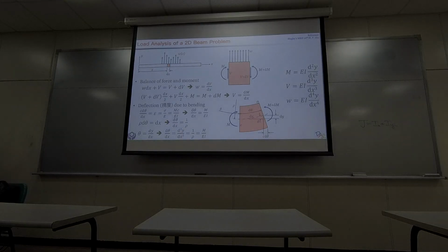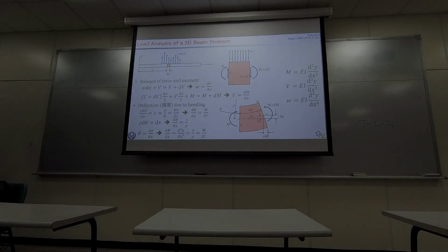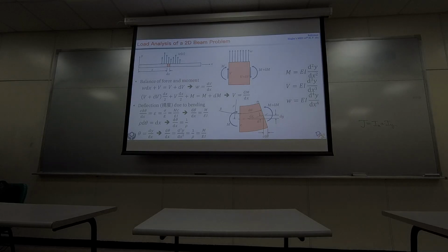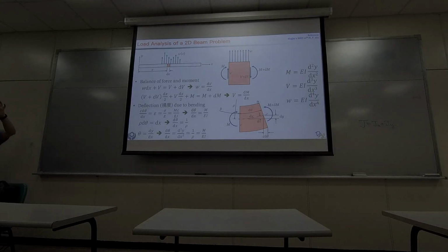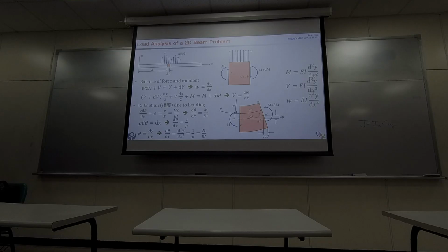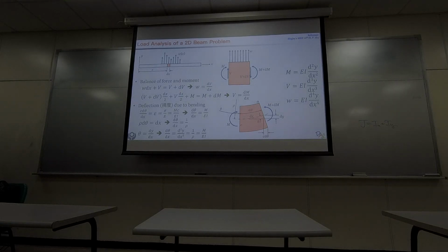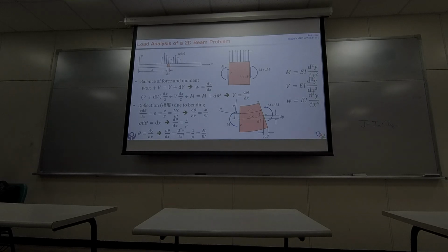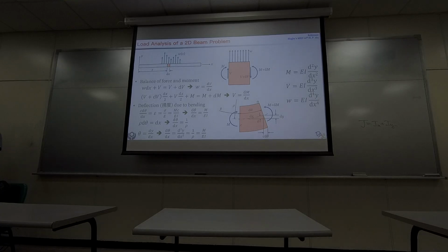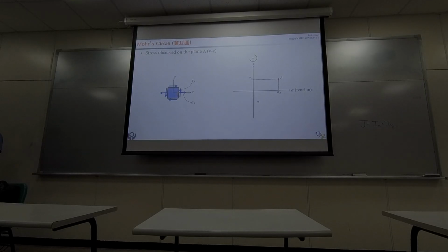Now, actually I feel like this is a very troublesome problem, like a beam problem, okay? You remember this, right? You need to draw the shear diagram and the bending moment diagram. Do you remember? I really don't like this part because it's easy to make mistakes. It's fun, but you can easily make a mistake. And I feel like for the entire book, this is the most difficult part because the entire calculation takes a long process. But it's very important, because you need to know which point is carrying the most load.